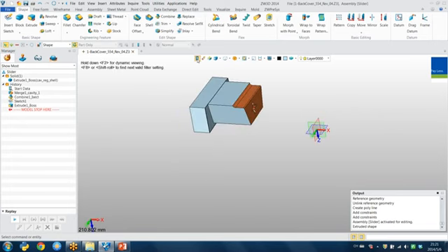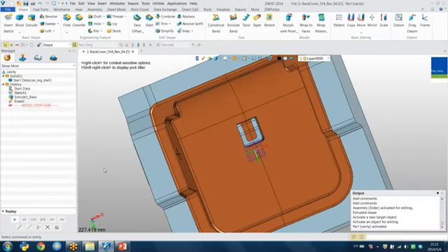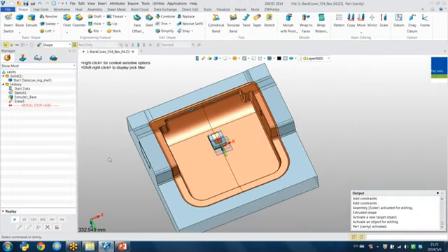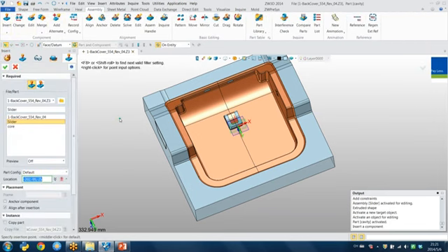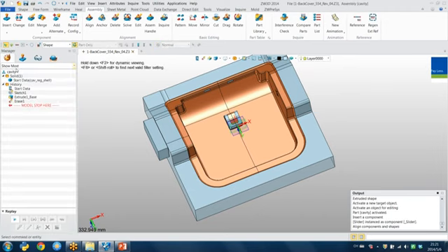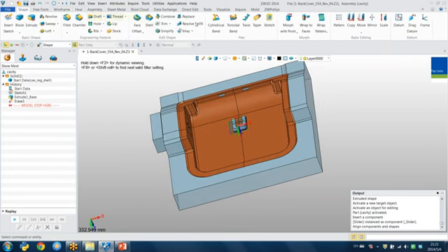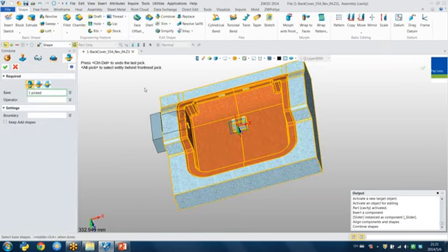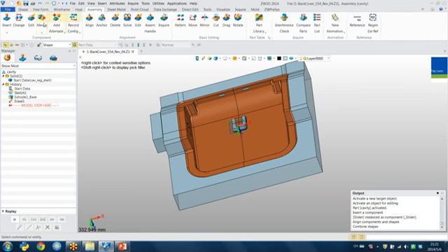So then for the cavity, I can do the same. Insert the slide. So I can use the combine functions and use remove. Oh, merge in the slide first. I can merge.